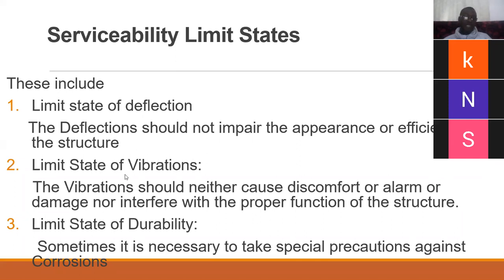Second, the limit state of vibration. For structures that are subjected to vibrations, like machine foundations, for example, members supporting transformers and others, the vibrations should neither cause discomfort nor damage to the structure itself, as well as all structures that have been constructed or will be constructed near that structure.